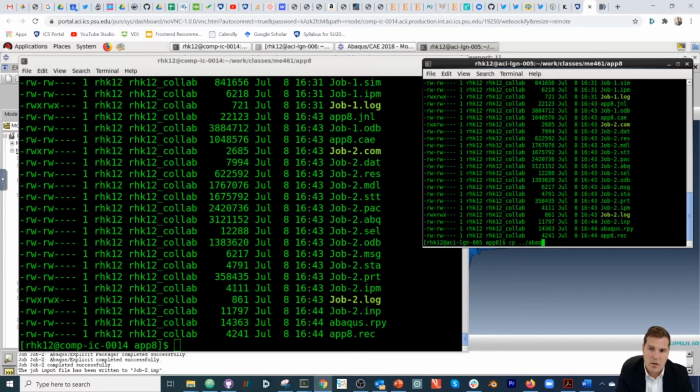Abacus, or it's app7. App7 is a directory /abacus_app7. I'm going to copy that here. So what does this say? It says copy one directory back and then go into app7 directory and copy a script called abacus_app7.pbs space dot. The dot means to here. We can actually rename this if we do abacus_app8.pbs if you want to rename it. You don't have to. Push enter.